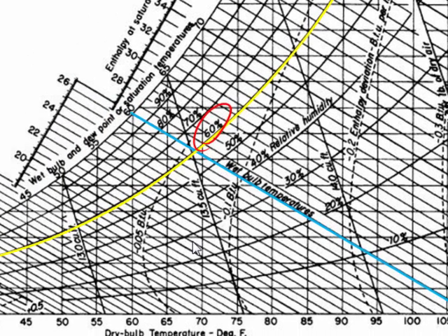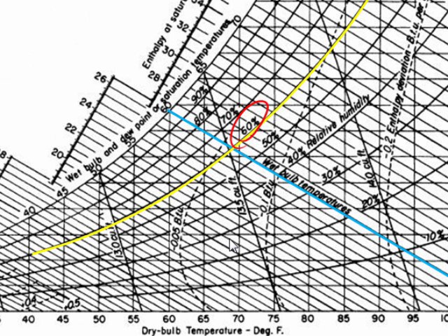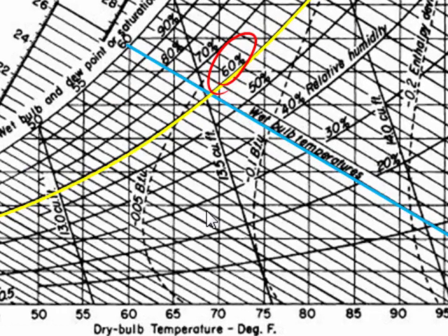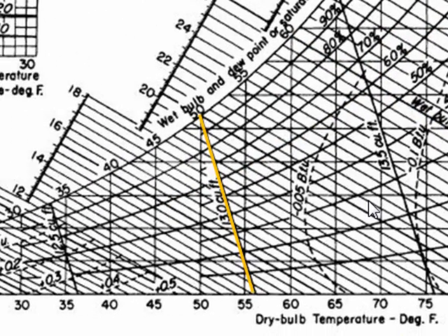The relative humidity line, for which the value is in percent. As you see, the line shown is related to a relative humidity of 60%. Specific volume line with values in cubic feet of moist air per pound of dry air. The line here is related to a specific volume of 13 cubic feet per pound of dry air.